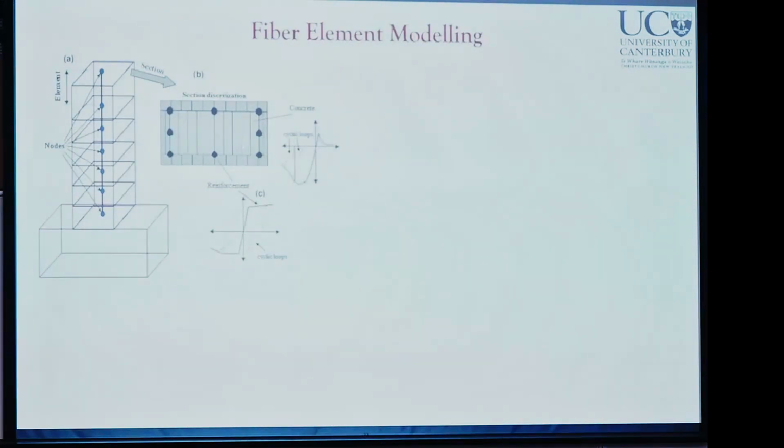So we are looking for a structural model that can directly, this was actually our purpose during the research, can directly not only estimate the sideways mode of collapse, but also the vertical mode of collapse. To that purpose, we did a little research and literature review, and we realized that we can actually adopt a fiber element modeling technique to simulate both modes of collapse.